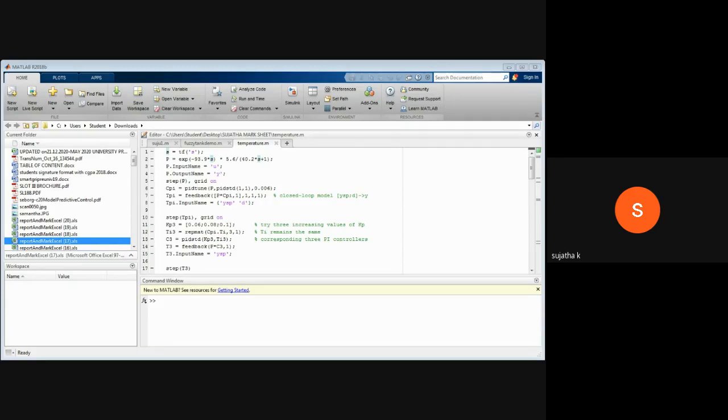Then you want a process. You have to visualize the output. For that you require a CRO, right? So CRO is your scope. So I'm taking a scope and placing it. Scope means that is your CRO actually. This is the input, where you can connect any block to the input of the CRO. And this is a multiplexer, where you can add up two signals together.